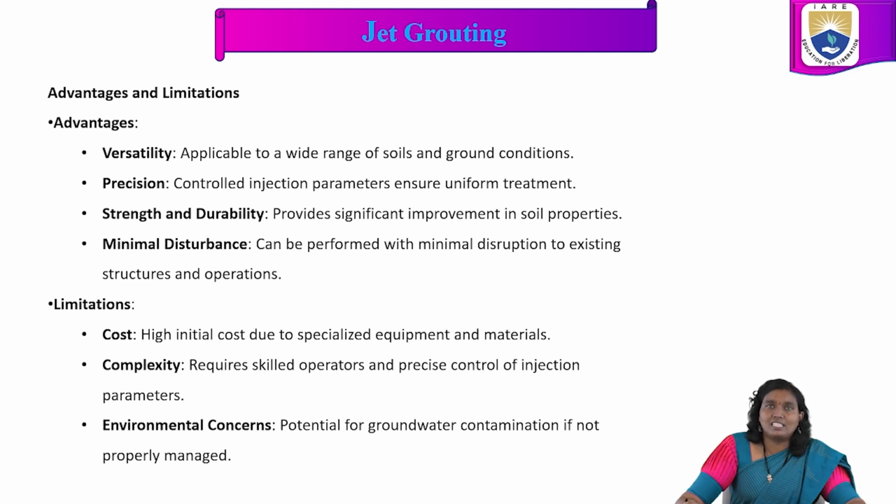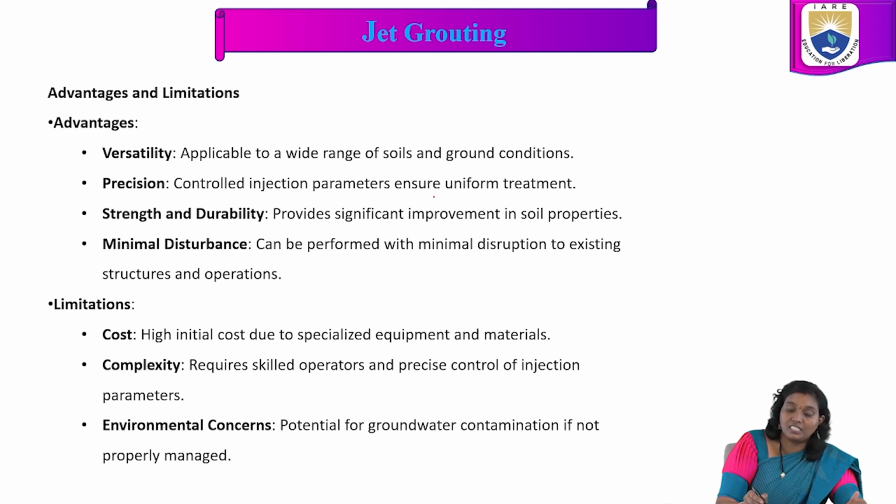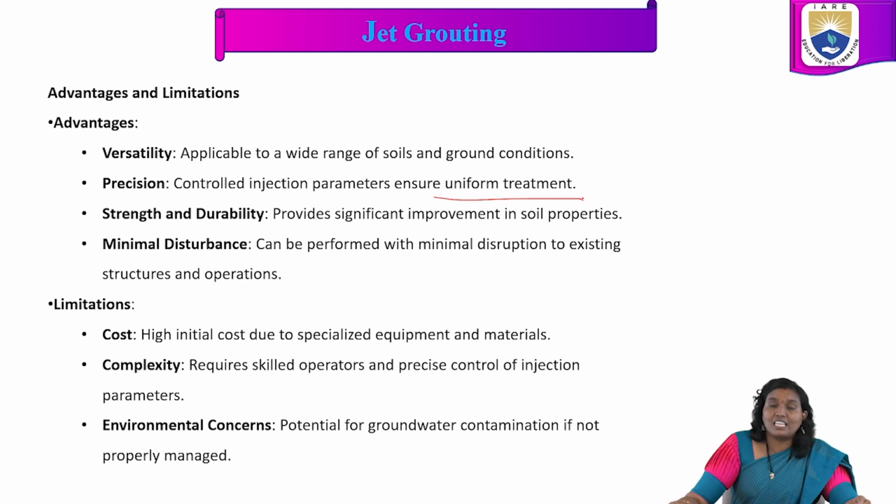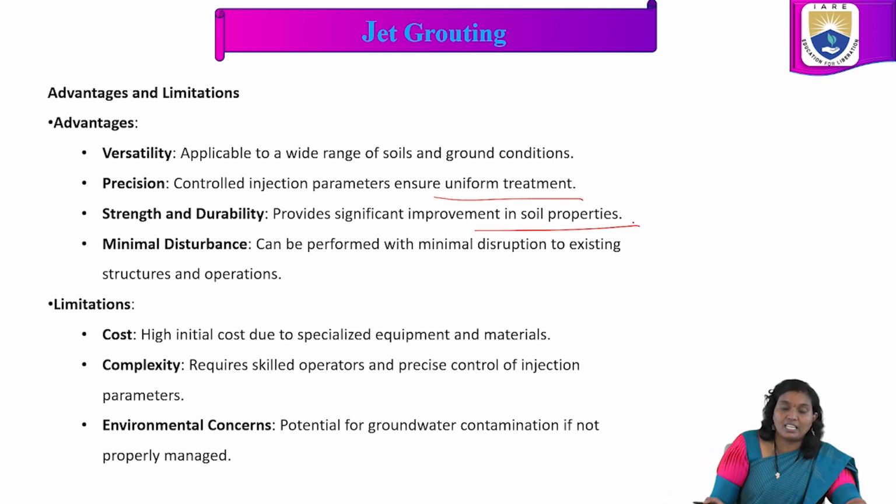Advantages: versatility, precision, strength and durability, minimal disturbance. It can be used in a wide range of soils and ground conditions. Controlled injection parameters ensure uniform treatment and precision. It provides significant improvement in soil properties. It can be performed with minimal disturbance to the existing structures and operations.